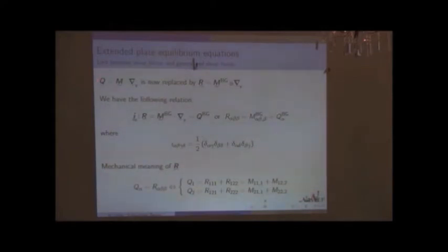It's just an analogy. The shear force is the divergence of the bending moment; I call this the generalized shear force because it generalizes this idea, and we will see this is very explicit in the following. It's better to look first at the indices. Q is the divergence of the bending moment. From the very definition of the generalized shear force, you can retrieve the shear force by taking the trace over the last indices of the generalized shear force.